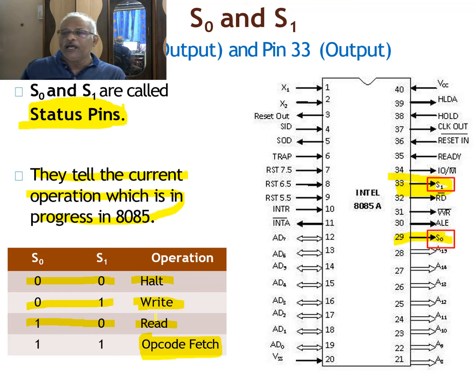Suppose I have written 100 codes for a particular program. The 8085 microprocessor doesn't have its own memory to handle those 100 codes. Therefore, I will have to write those 100 codes into consecutive memory locations. I will choose a particular memory location and start storing all the operation codes one by one. Once the operation codes are fed into the memory, I will ask the microprocessor to go to that particular memory location and to fetch. Fetch means to pull, to have the operation code.